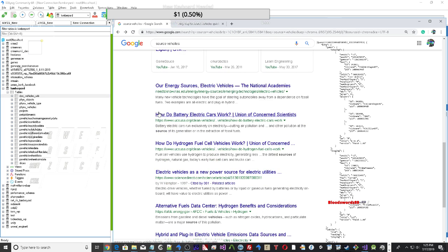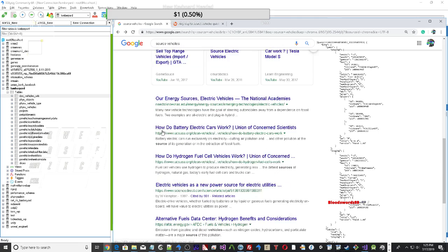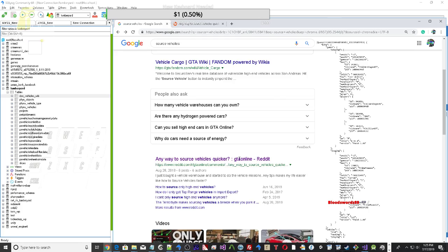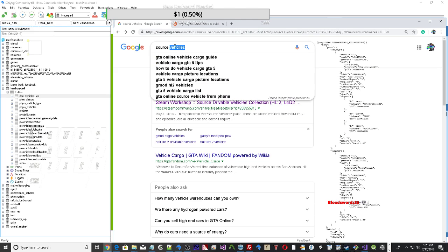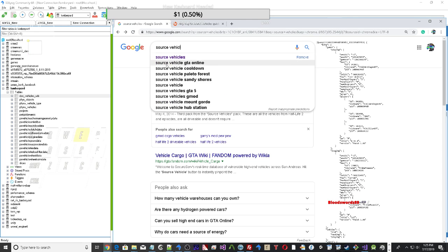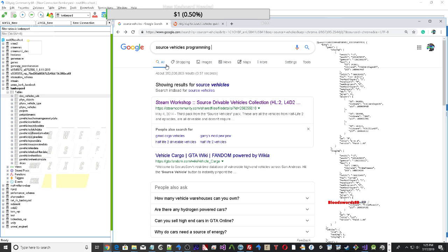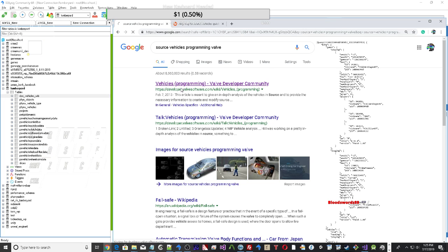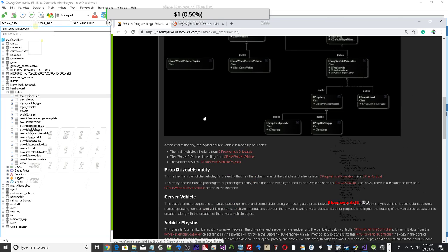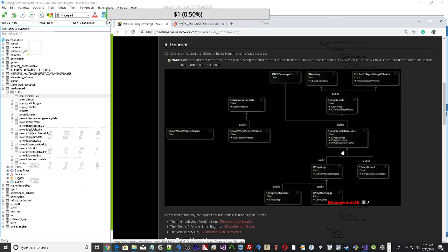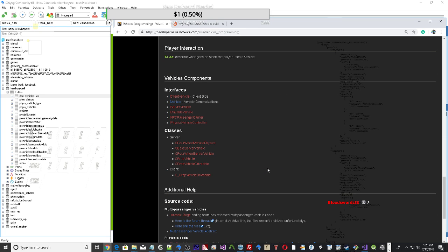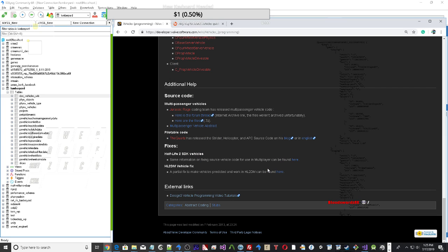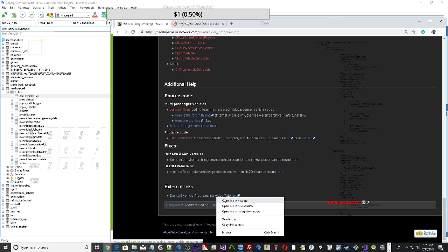PhysX vehicles make use of scene query filter shaders to eliminate intersections with the vehicle issuing the raycast, and with any geometry that is not to be considered as a drivable surface. More details for how to set up myFilterShader can be found in section filtering. For a batch containing just a single four-wheeled vehicle, the suspension raycasts can be performed with the following pseudocode. PxVehicleWheels* vehicles[1] = myVehicle; PxVehicleSuspensionRaycasts(batchQuery, 1, vehicles, 4, results).